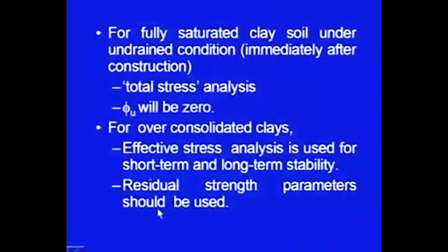In the past they have been over consolidated. So, for them effective stress analysis is used for short term as well as long term stability, but instead of using the peak shear strength parameters, the residual shear strength parameters are used in the analysis. These are important points which we have to remember.